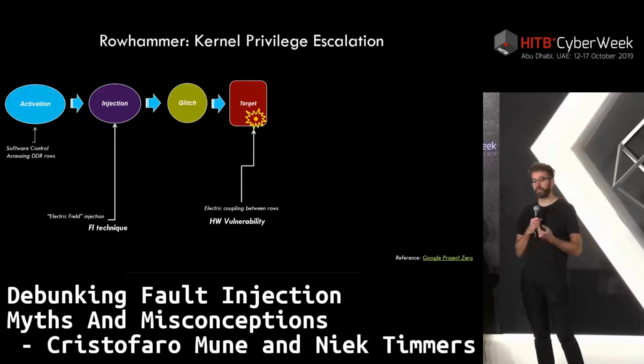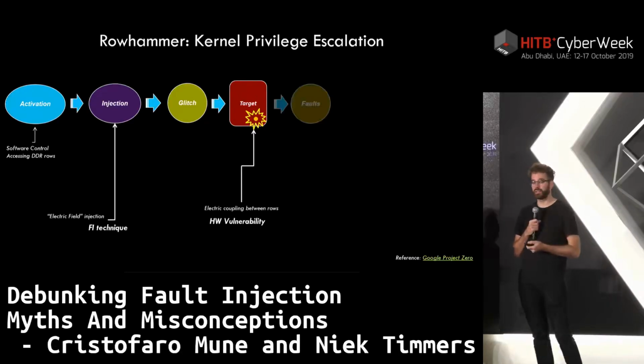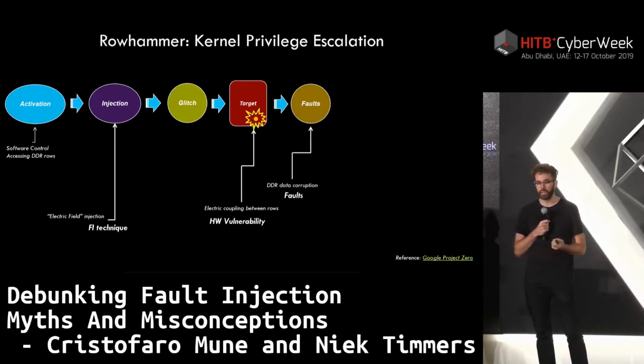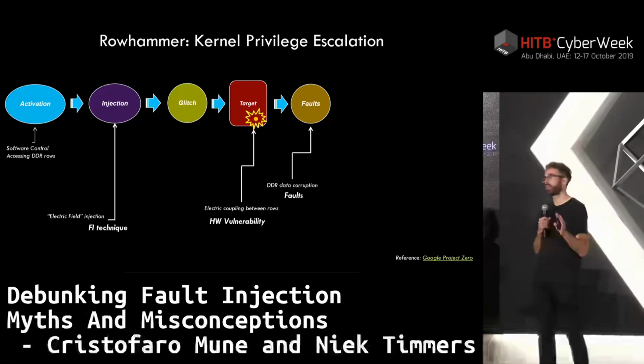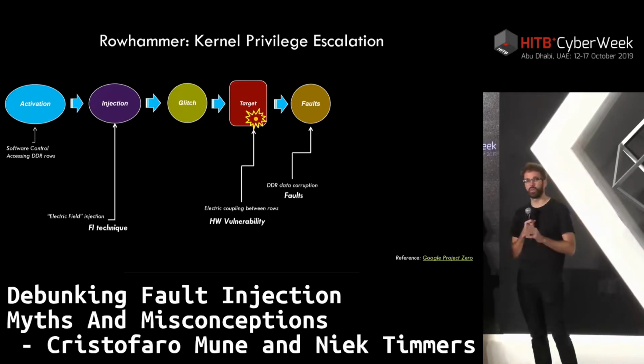So if we have found the right location, we can actually inject a glitch that manifests itself again in a fault. And in this case, we are actually corrupting the data that's stored in an external chip. Because it's important to realize we're now not talking about the microcontroller or the system on chip. We're talking about injecting faults in an external memory chip.